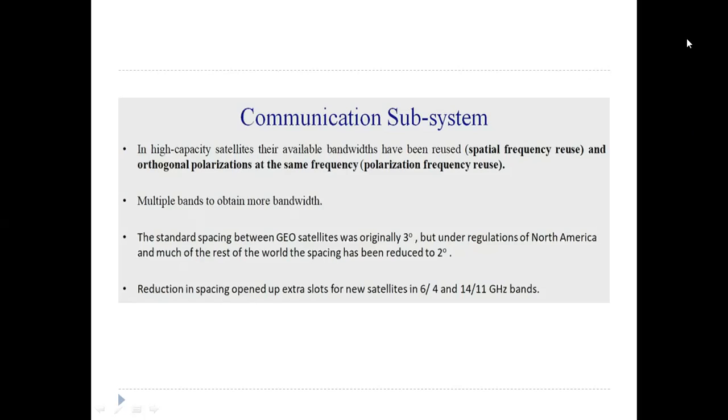However, propagation in rain becomes a major factor at frequencies above 10 GHz. Attenuation in rain increases at roughly the square of the frequency, so at 20 GHz, rain attenuation is 4 times larger in dB than at 10 GHz. It is almost impossible to provide a rain attenuation margin larger than 20 dB in any system, and many Ka-band systems will have a margin of only 4 to 5 dB when operating to a small earth station antenna.